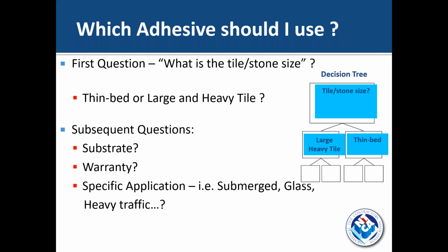Is Multimax Light sufficient adhesive for smooth back thin porcelain panels? Yes, yes. We have several products that we recommend for gauged porcelain tile panels. Multimax Light, 257 Titanium and 254 Platinum are all very good for that application.